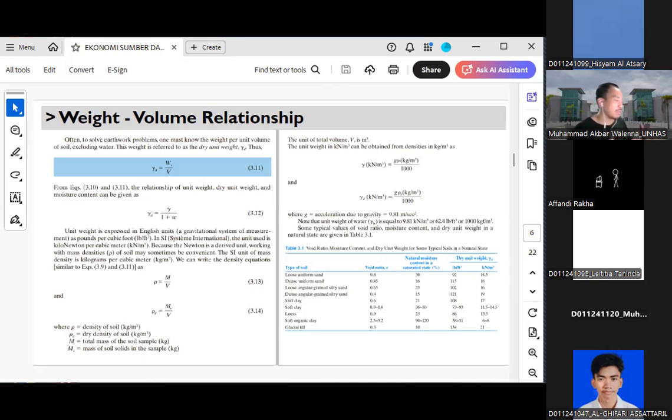Okay, so when it comes to the table, I think it is quite easy for us to infer that the sands or the granular materials are denser, they are stronger. Okay, and that means that we can rely more on this type of soil. In terms of clays, they are softer, they are lighter, they contain more water, and that's what we really need to worry about.